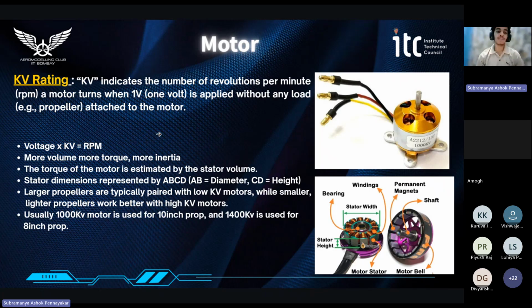More volume results in more torque and more inertia. More inertia means the motor responds slowly: it accelerates and decelerates slowly.